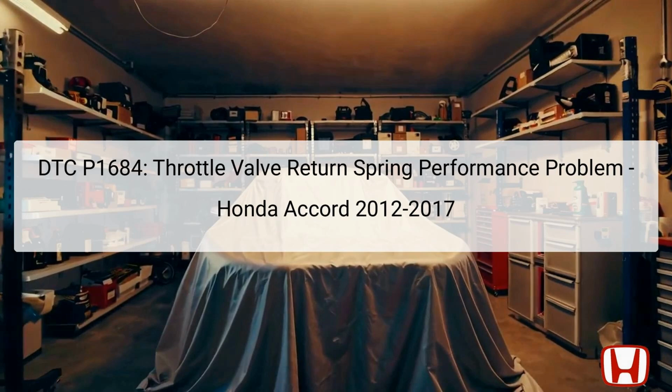If the return spring fails to function properly, it may lead to unresponsive acceleration or inconsistent throttle operation, impacting vehicle performance and safety. The throttle body is typically located between the air intake manifold and the air filter box, making it a key area for inspection. This troubleshooting guide will outline the symptoms, possible causes, and step-by-step troubleshooting procedures to effectively address this issue and ensure the proper functioning of the throttle control system.